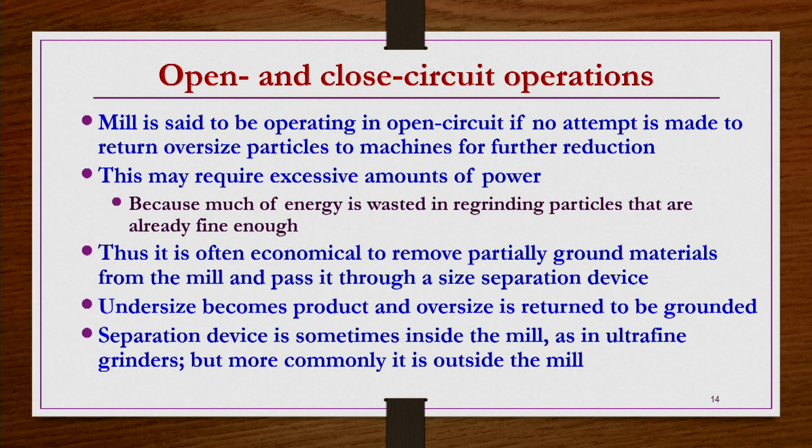The separation device is sometimes inside the mill, but in general it is outside the mill. We have ultra fine grinders, like hammer mills with internal classification. In such arrangements, we have the classifiers or separation devices inside. So, the separation device may be inside the mill, but that is not possible for all types of machines. Commonly these separation devices are outside the mill.